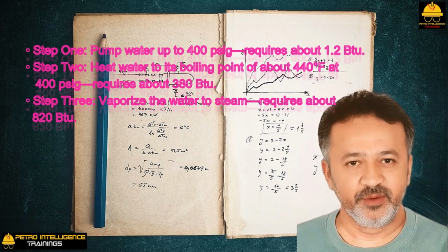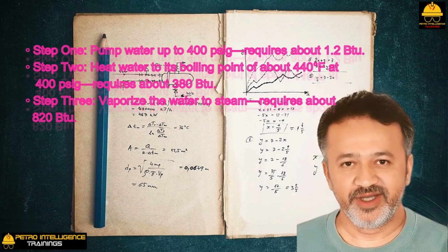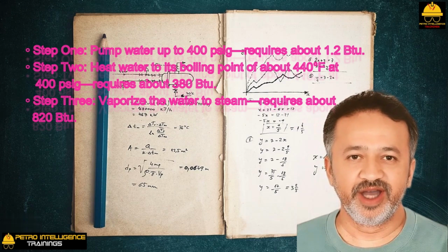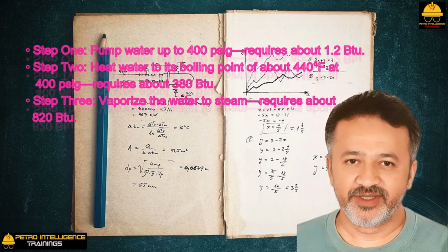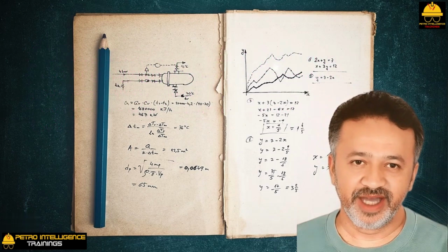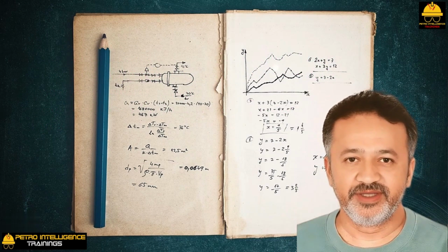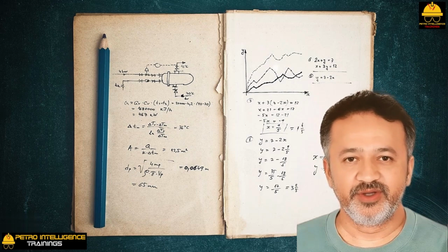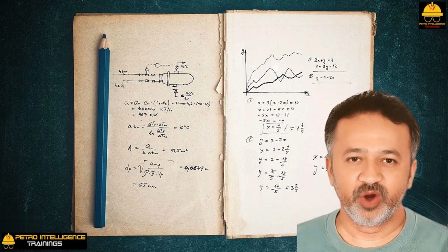Any boiler plant operator trying to optimize steam generation efficiency will worry most about the firebox and convective section economizer, and not the boiler feed water pump. About 2/3 of the energy required to generate steam is devoted to latent heat and 1/3 to sensible heat. The energy needed to increase the pressure of the water is very small in comparison.